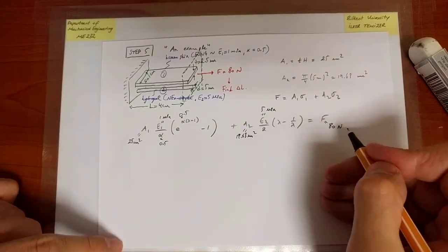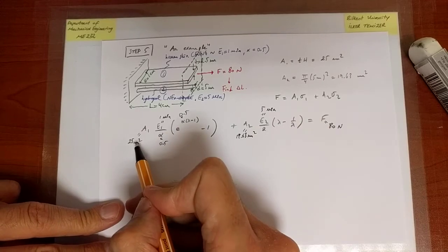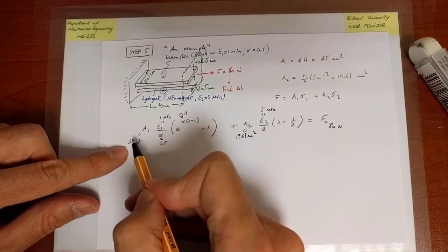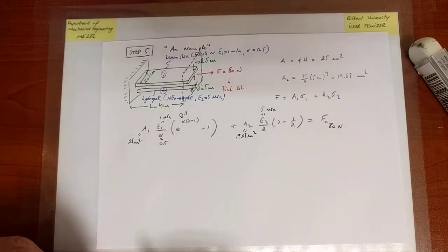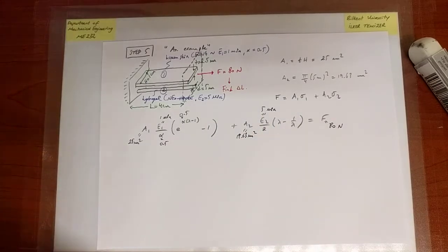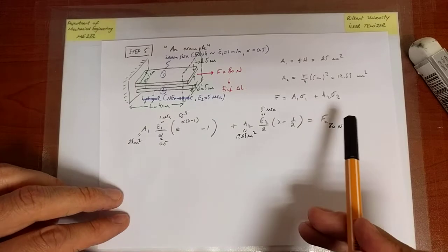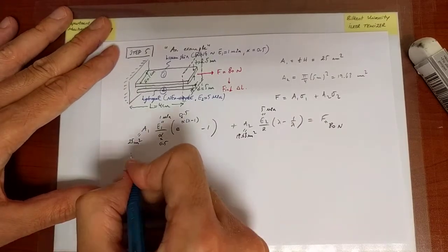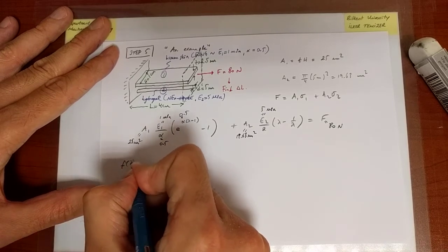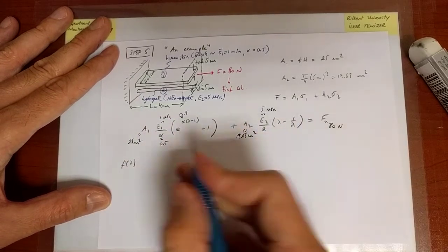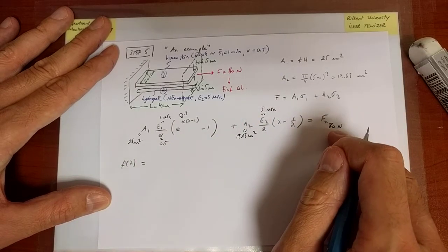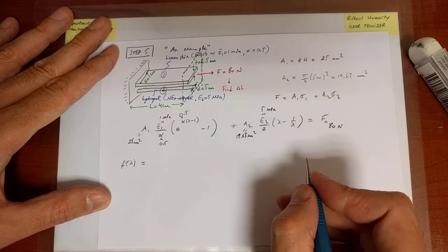So that's equal to 80 newtons. Now notice that millimeters squared 10 to the minus 6, MPa 10 to the 6, they cancel each other, so I'll just retain the numbers and throw off the units. That's consistent with newtons on the right-hand side. And then I will put this 80 to the left-hand side and call that equation F, which is now an equation of only the remaining unknown, lambda. I'm trying to find lambda such that that minus 80 is equal to 0.